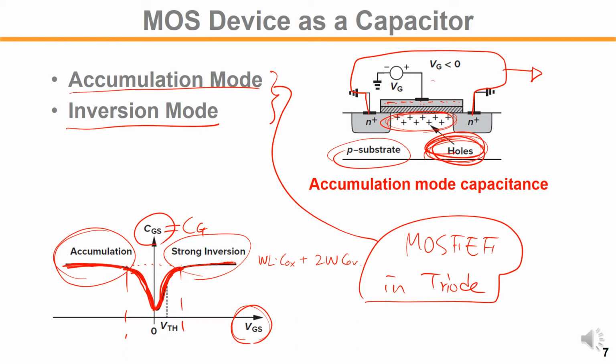For example, you implement a capacitance in an LC or RC low pass filter. So you're driving your signal onto this low pass filter. If your signal is moving around this operating region, then the output signal will see a pretty constant capacitance. But if your signal is near ground, moving up and down, then it is seeing this kind of large capacitance variation, so your output will be distorted.